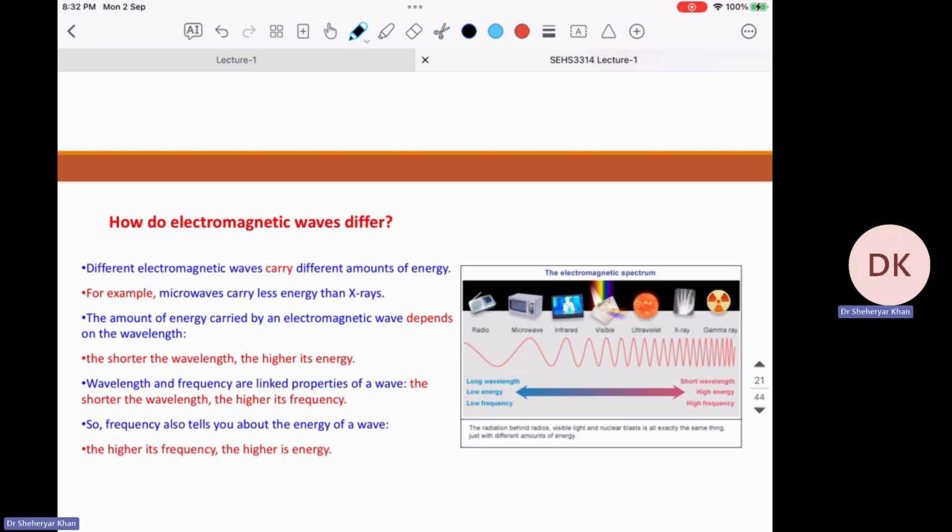So there's a source, right? Source is the transmitter, load is the antenna, right? So you need to make sure that the impedance at this terminal is equivalent to this one.